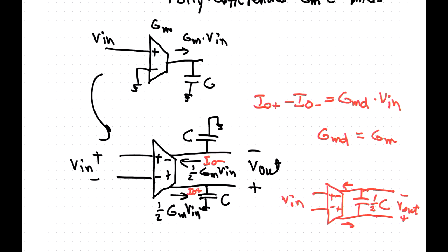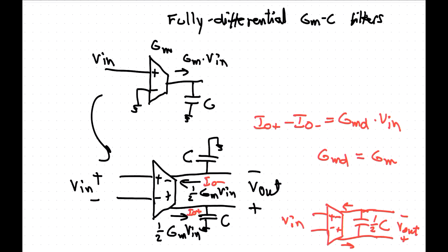But if you do that, and there's a common mode feedback and you're relying on that capacitance for stability, it's not going to help you in common mode, as we talked about for the op-amps. So this is really the fully differential type of transconductors.